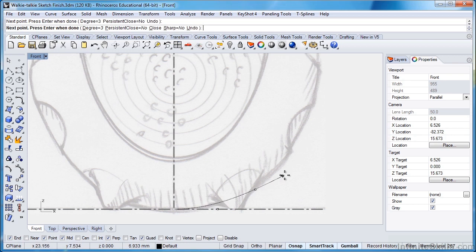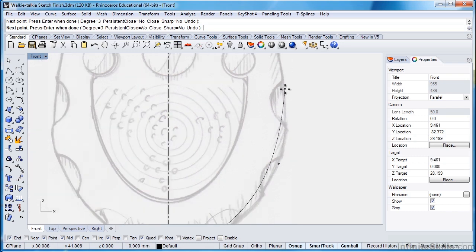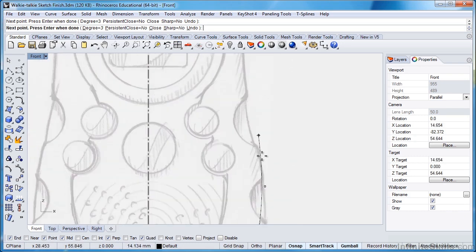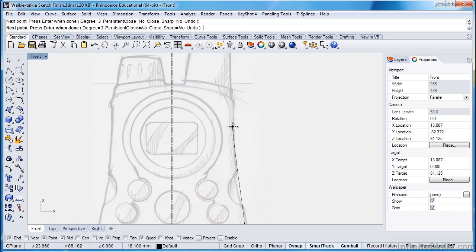And then I'll add some clicks. Now Rhino's a little different to draw coming from Illustrator or something like that. And what you do is as you're drawing, you're just going to kind of draw close to what you want at first, and then we come back in and we're going to edit our curves. And I try to do this without adding too many curves. And I'm also going to draw my curve above and beyond the actual body that I want. So I'm going to make my last click up there, and then I'll press Enter to finish applying that line.